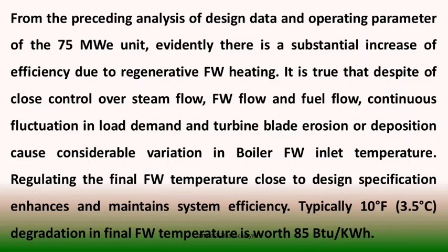Sometimes we find deposition in the blade that affects the heat utilization from the steam during the expansion in the turbine. So naturally there is a variation in boiler feed water inlet temperature under different conditions of regenerative feed water heating or the process of heat transfer.